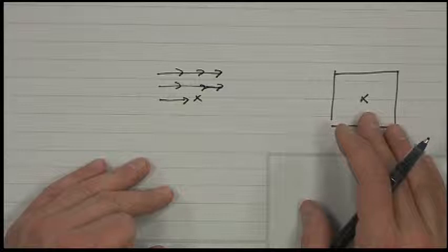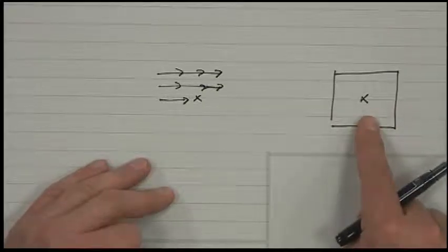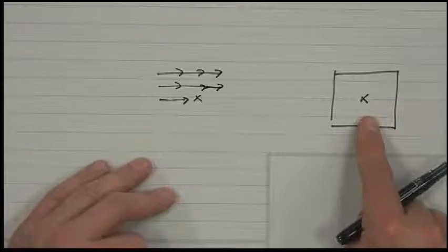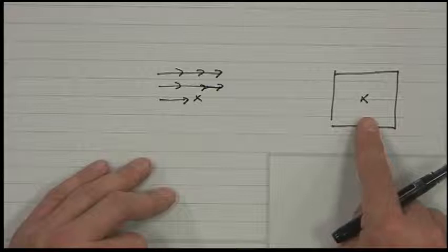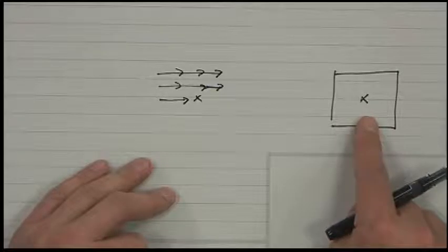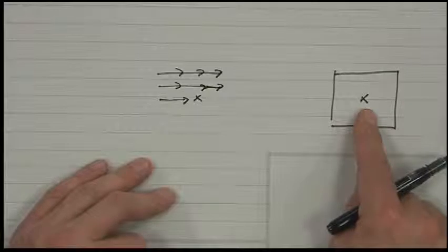The pluses are that it's simple and direct, and designing it is straightforward. You pick the frequency response you want, take the inverse Fourier transform to get the impulse response, and window it with, say, a Hamming window. But the downside is that the computation can be massive for implementation.